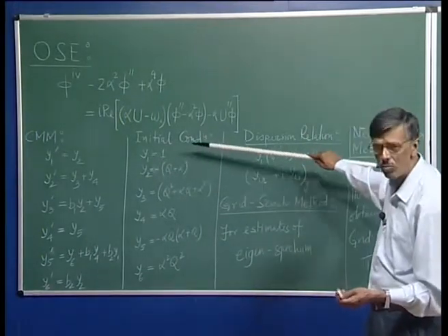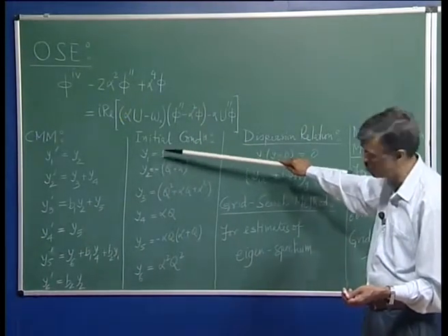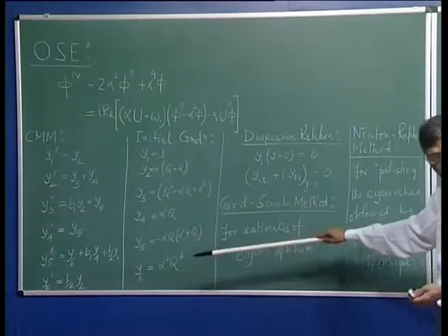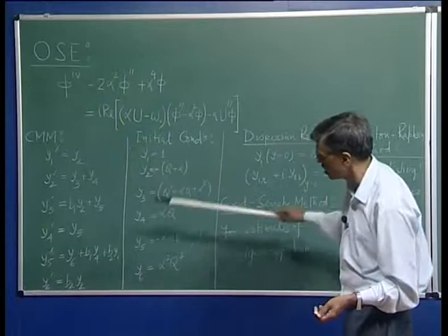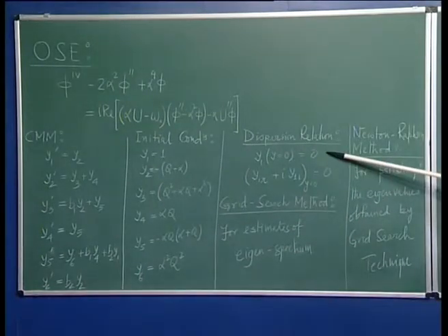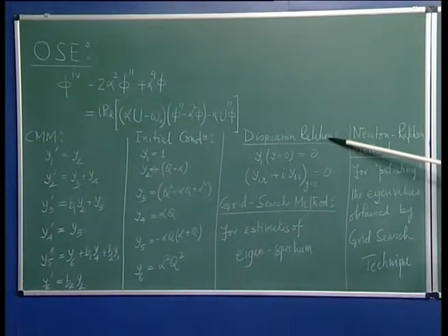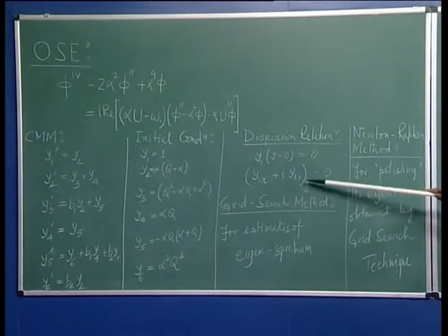So, that is what constitutes the initial condition. We have normalized them with respect to y 1 and we get the 6th condition, right. And so, what you do is you start solving these 6 equations with this initial condition and come up to the wall and investigate if y 1 is equal to 0 or not. That is what we call the dispersion relation, and so that will have a real part and an imaginary part.